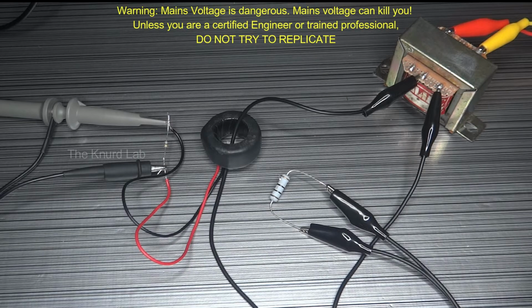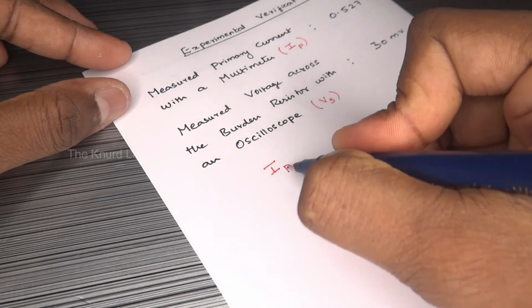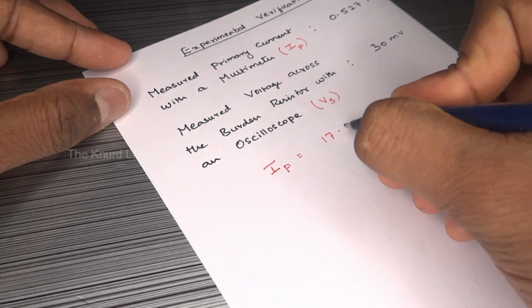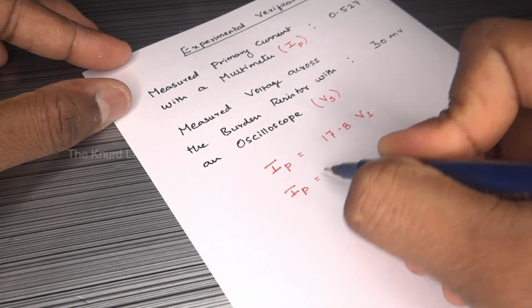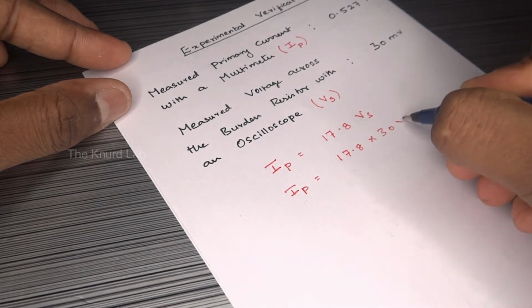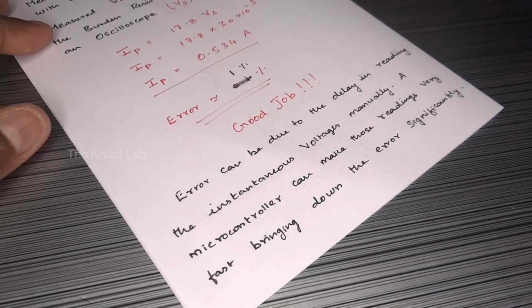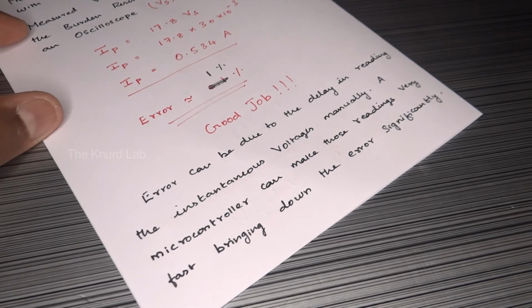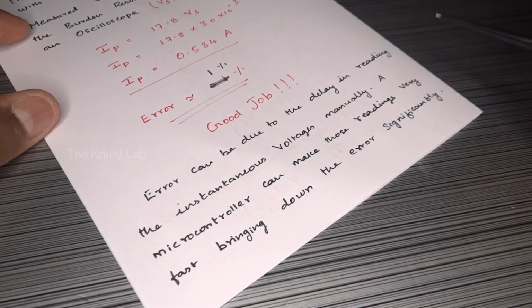Using the same setup that we used earlier to calculate the turns ratio, I just recorded the primary current using an ammeter and the secondary RMS voltage using an oscilloscope. The primary current was 0.527 amps and the secondary RMS voltage was about 30 millivolts. Now, using the expression that we just found out, I calculated the primary current to be 0.534 amperes. And we were able to calculate a current with a tolerance of just 1%, and that too manually. If we could do the same using the ADC of a microcontroller, which is not only more accurate but faster, I think we could achieve more accurate results.